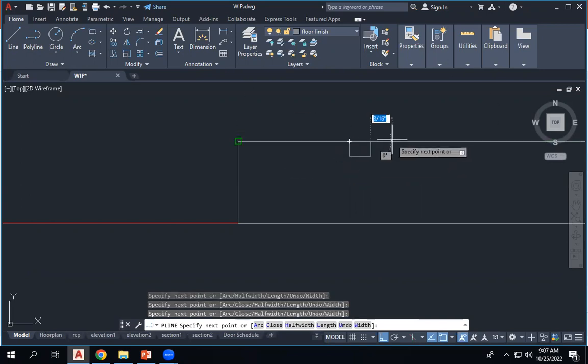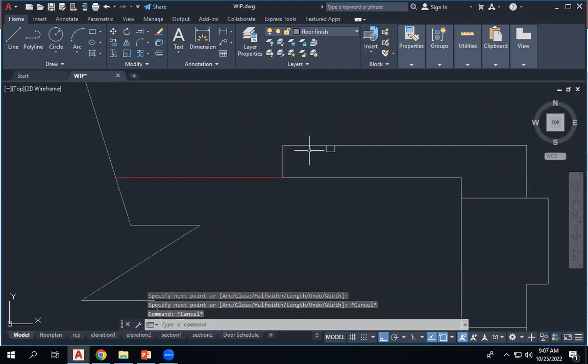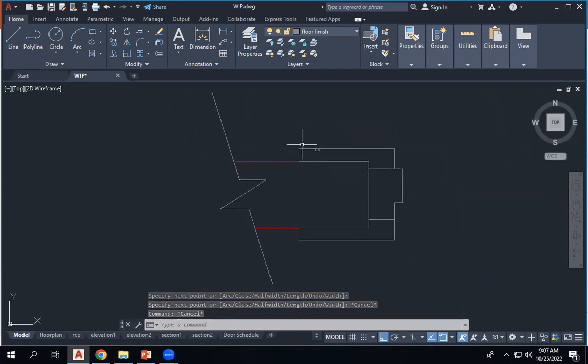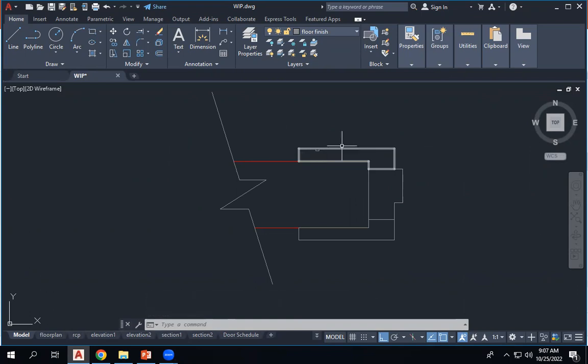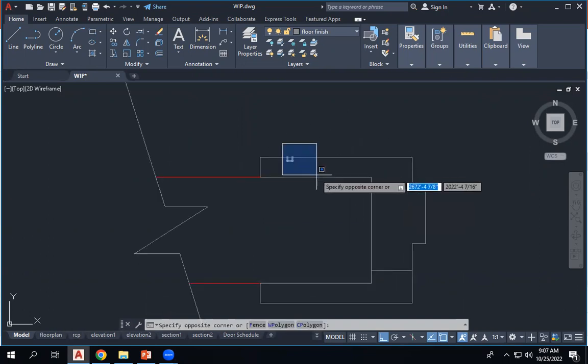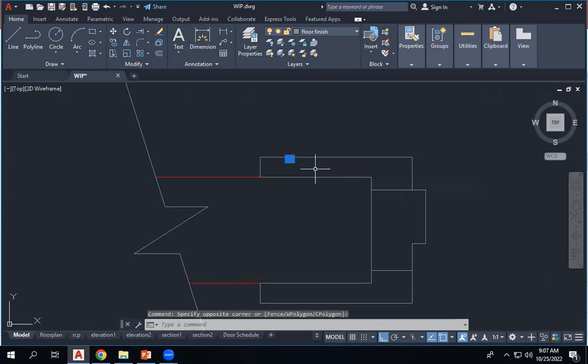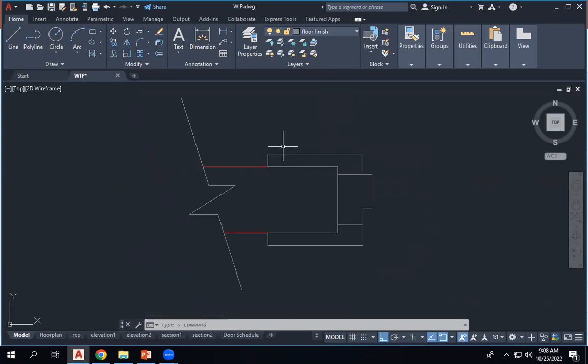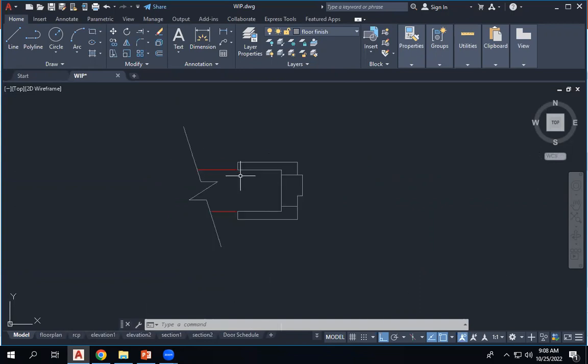This. So you can give the dimension, but you can show it in here, but don't give any dimension here. You can just enlarge this detail and give it separately. That's also fine. For the door window for the detail drawing, you can just indicate like this. But if there are any grooves, you have to give a separate drawing for that. Otherwise, the contractor will do straight away like this. So we need to do a separate one.